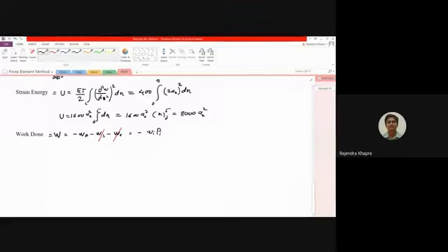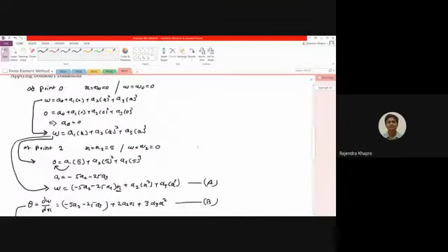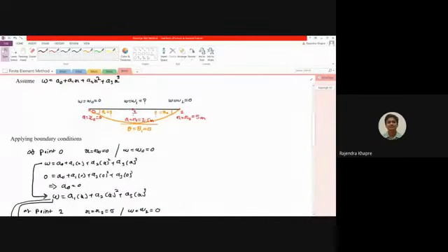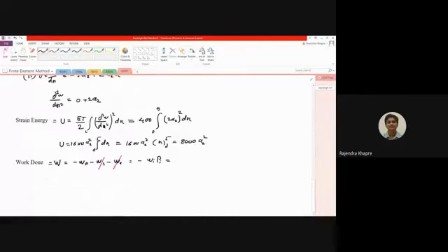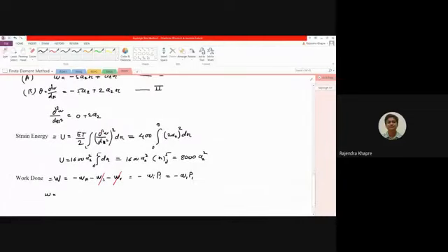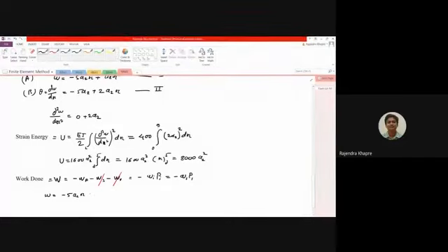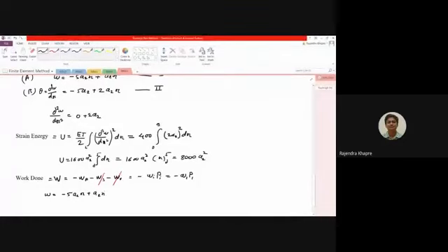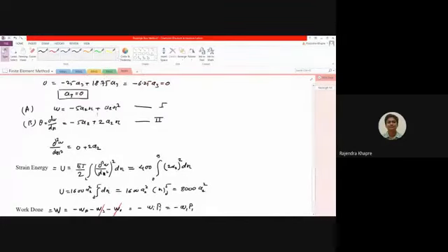at that particular point. Right now if you see the problem, your load is acting at point number 1. So I am just rewriting this term as W at point number 1 multiplied by load at point number 1. I need to first of all calculate what is the W at point number 1. If you see the earlier case, your W value is minus 5 times A2 into x plus A2 into x square. This is the final expression for the value of W.